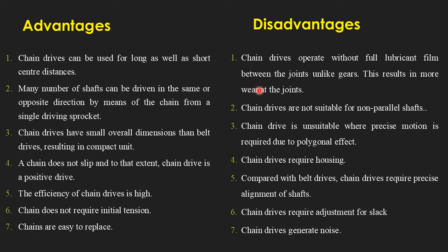Hence the wear will be higher in the case of chain drives. Wear will be present especially at the multiple joints of the chains, especially between the link and the bush. At those points we will see the wear.